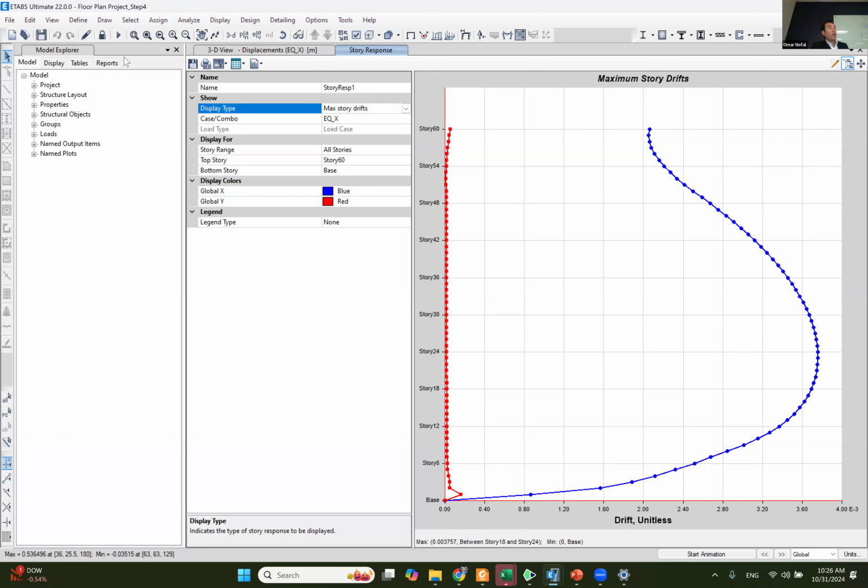There's something I also want to tell you, which is the modal analysis. Do you guys remember the mode shapes that we talked about for the building? Like we said, if this is the building, it can have a mode like this, a mode like this, a mode shape like this, right? So all these mode shapes that the building can do, and each one has a period. The fundamental period is the period of mode shape number 1.